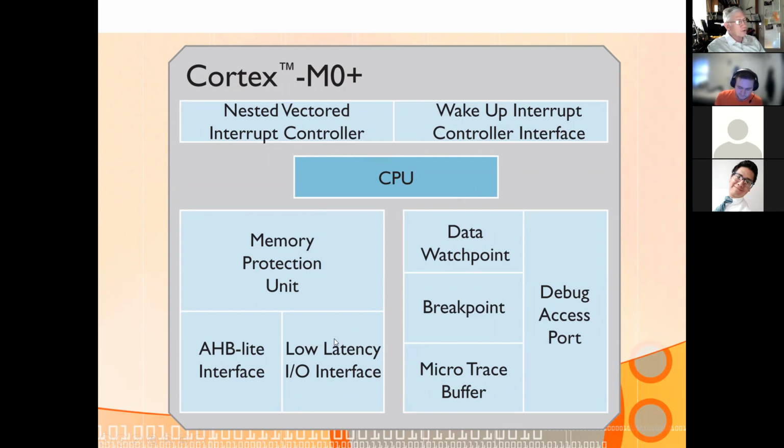There's no place where it spells out how to take advantage of this. But what happens is the GPIO ports are mapped to two different places in the 4 GB memory, and in one place they're the standard access, and in the other place they're the high-speed access.